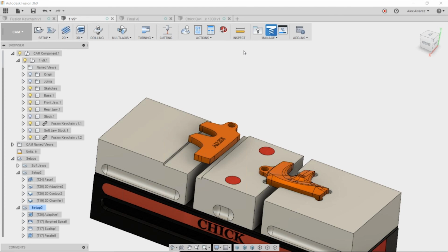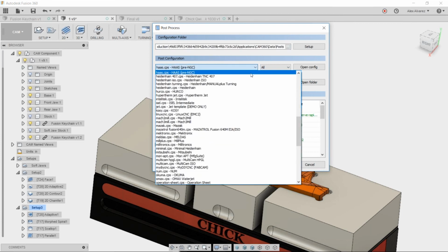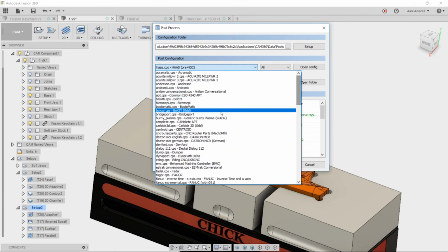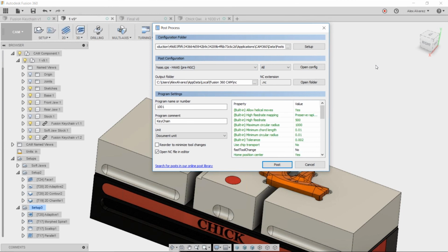We also have a question from Adam. He's asking how do you know if my machine is going to have a post processor here in Fusion? You can either go up here to the post processor tab and check to see if there's a post for you. You can also go online and type in Autodesk HSM post processors, and there's an entire list there with all the posts available to you. What we've done in the past is find a post that's similar to the code that your current post is giving, and then modify that post inside of Fusion to give you something similar.